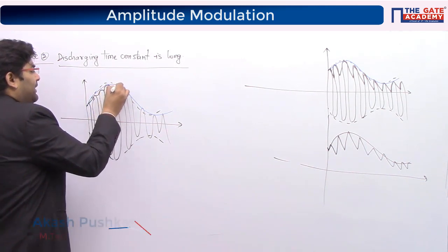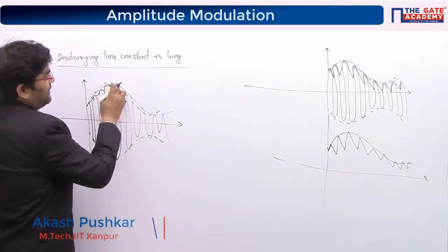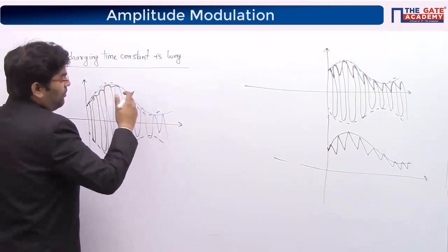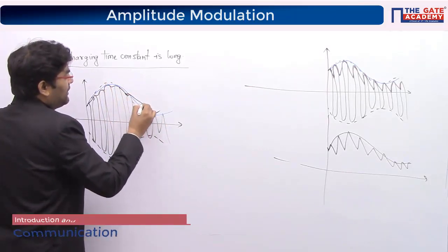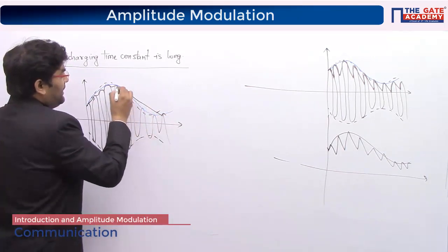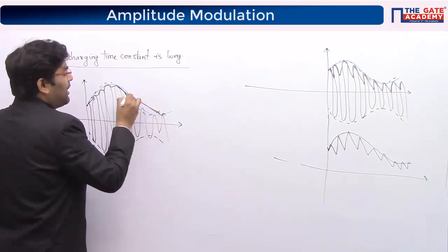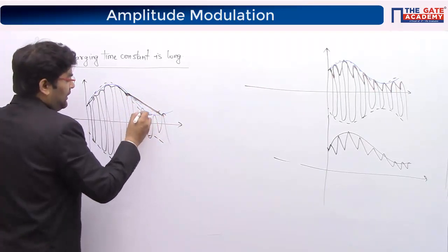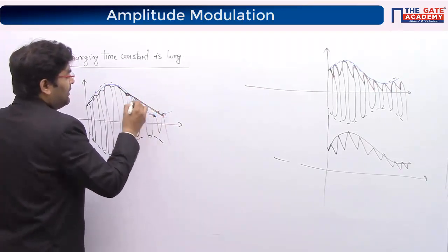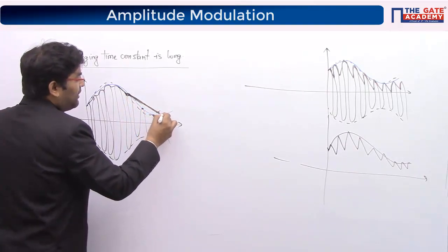Okay, take it. But now what is the problem? This is going very low. The AM signal is going very low, but it will slowly discharge, and after that it will reach and then it will pick it. So what is happening here? You see this diagonal line, can you see it? It is diagonally jumped because none of the points is giving more value than this. It will slowly keep continuing to discharge until it reaches here, and then you get another, more positive value. You charge a little bit more.